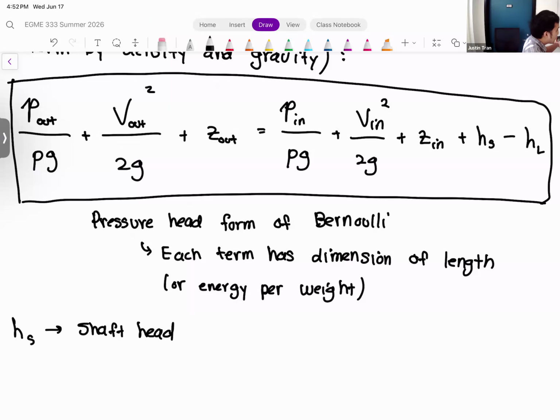The origin of that term is that when you measured pressures or energies in a fluid, your manometer would go up or down by a certain amount, and that would usually be called head. So shaft head here represents the mechanical work that's done either on the fluid or by the fluid.